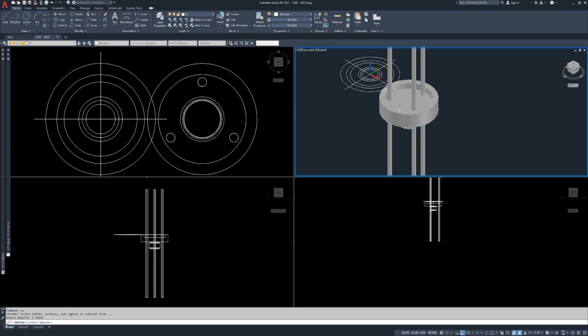So I'm going to select it in the southeast isometric. You can select it in the top, front, right side. It really doesn't matter. Once you have objects that are laying over top of each other, having the 4 views is very important because you can actually hone in on what you're actually trying to click. In the top view, you could be clicking anything up and down 20 objects. There's a command that actually controls that. We haven't gotten into it yet. I will get into it in a further video.